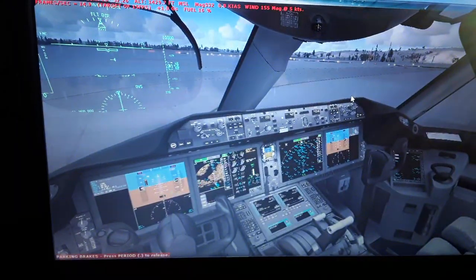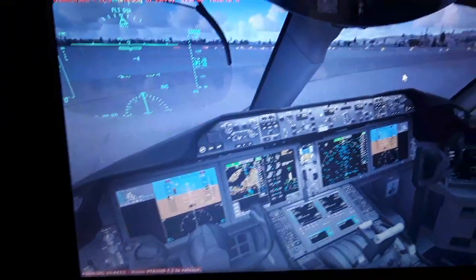We have also the navigation aids, VOR stations, ADFs, and the waypoints. The waypoints are horizontal and vertical navigation fixes with altitude and airspeed constraints. The aircraft is going to have to fly through some waypoints as we fly. So we select the waypoints from the flight management computer. We're going to be creating a flight plan later; you will see how. We have also the GPS position of the aircraft, the latitude and the longitude.